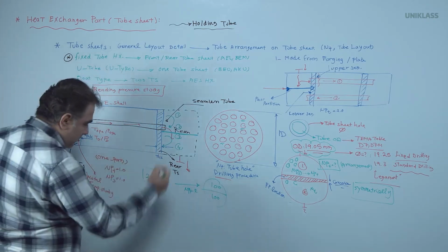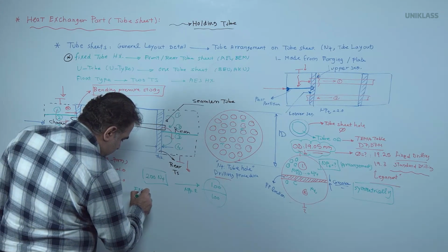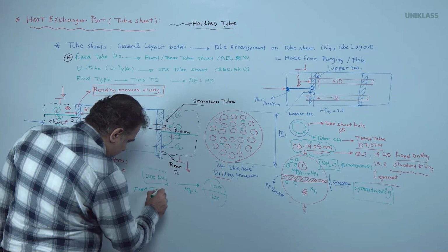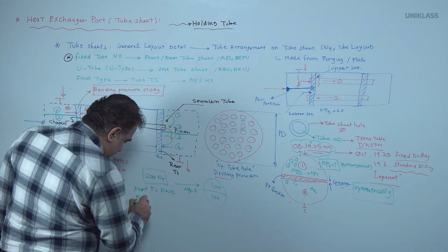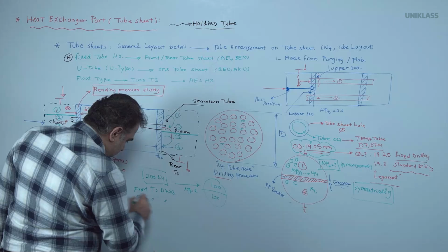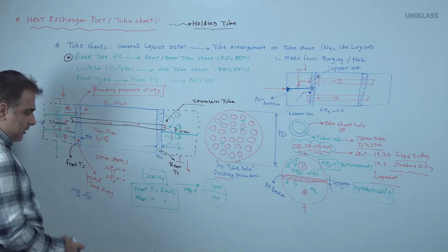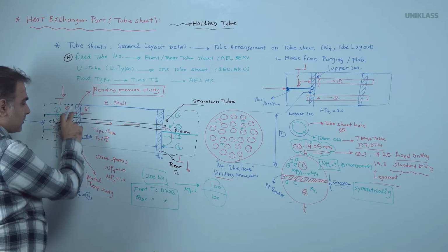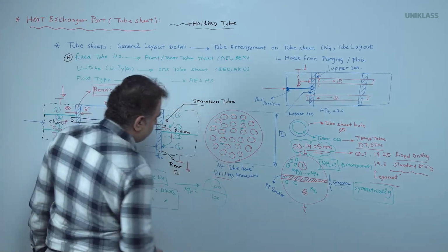Therefore, in the detail engineering job, we have two detailed drawings, front tube sheet DWG and rear tube sheet DWG. Material and type may be the same, but the detailed information for the availability of the groove on the path partition is different.